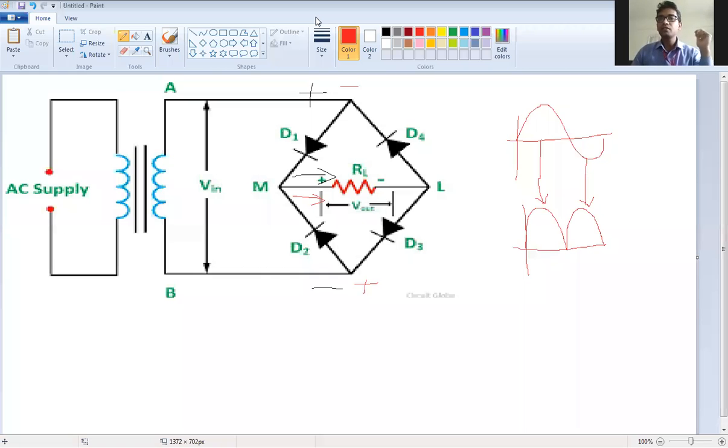Okay, now I'm audible. So here in this case, in half-wave rectifier, only one diode is there. So in positive half cycle, that will be on. In negative half cycle, that will be off. So obviously output is getting half of input. Hence it is called a half-wave rectifier. Then